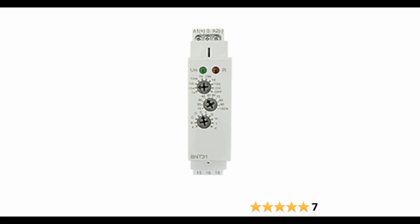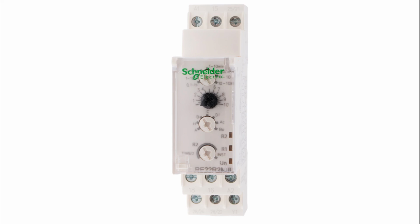Delay period. Once activated, the time delay relay starts counting down a predetermined delay period. This delay period can be set according to the specific requirements of the application. Load activation/deactivation. After the delay period elapses, the time delay relay triggers the switching mechanism. This mechanism can either activate or deactivate the connected load, depending on the type of time delay relay and its